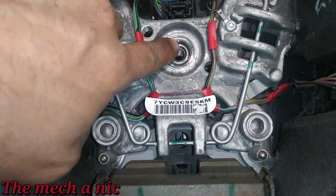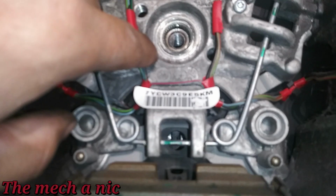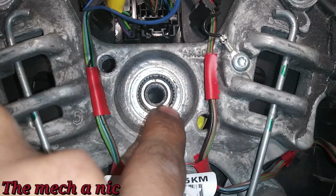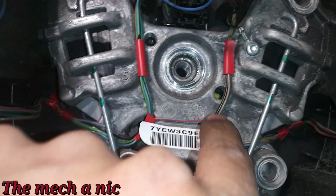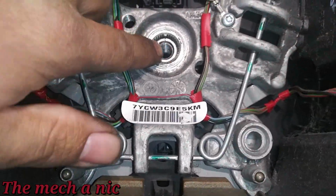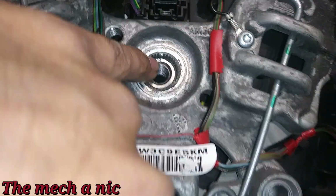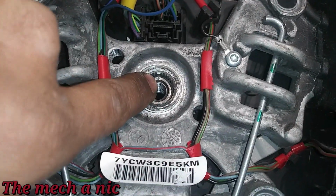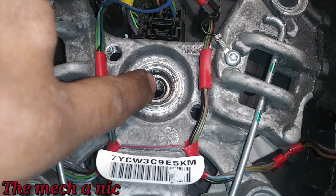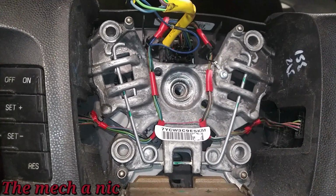Sure, you could go ahead and mark the steering wheel in correlation to the shaft, but honestly this thing is kind of keyed, so there's probably only two ways it could go on. Either way, the shaft has a little line right there. If you look up closely, see there's a line on it, and right above it there's a flat spot in the splines right there that lines up with that. So you can mark it if you want, but really it's kind of hard to mess this up.